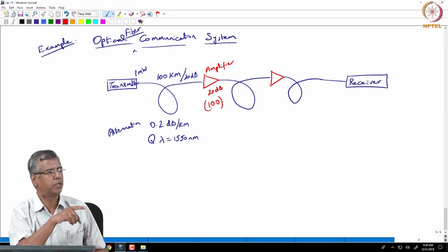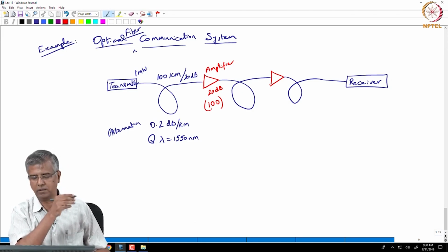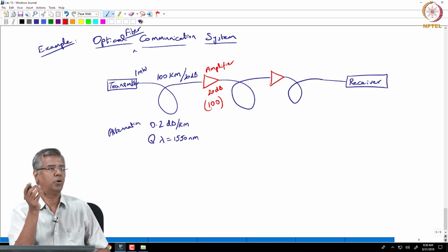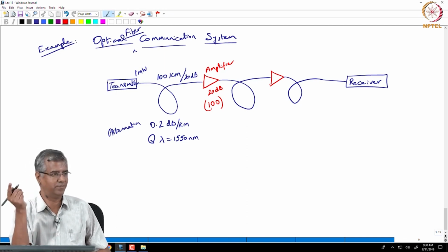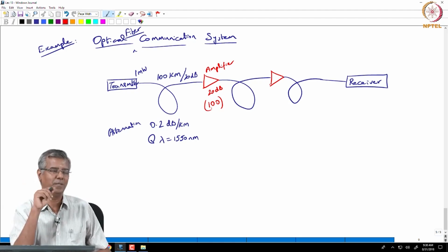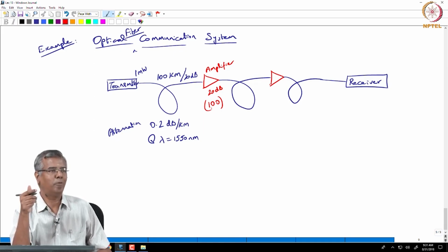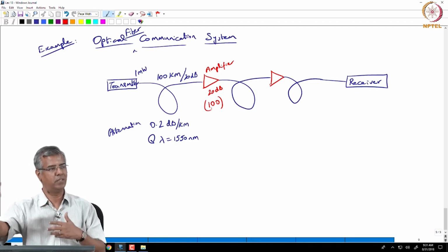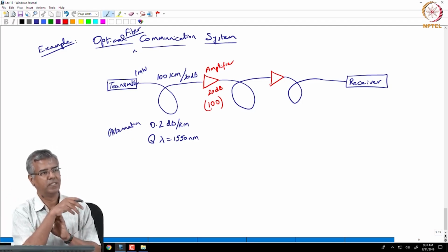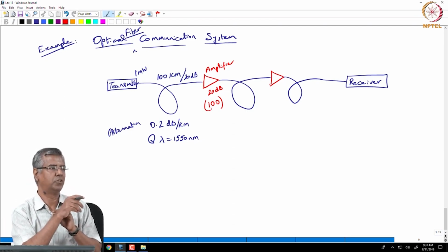But before I do that, you had a question. Sure. So, that is a very good question. The question is, the amplifier, just as we discussed a little while ago, might also have spontaneous emission, and that spontaneous emission could get amplified. That is the problem. Spontaneously emitted photons by themselves are not so much of an issue. They are getting amplified, right. So, they are also multiplying in number along with the signal photons that you want to amplify, and those are all just constituting noise, right.